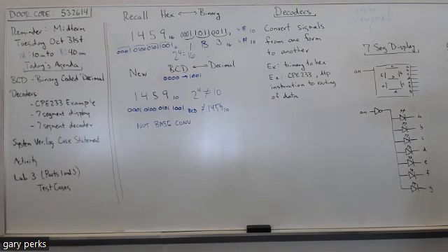Yeah, the mux right above this thing labeled reg file. So you see the outputs of this decoder, they're all going to muxes. You'll learn in that class that this ALU is basically a big mux. Well, specifically though, which input of the mux are those outputs going to? Yeah, they're all going to the select input of the muxes.